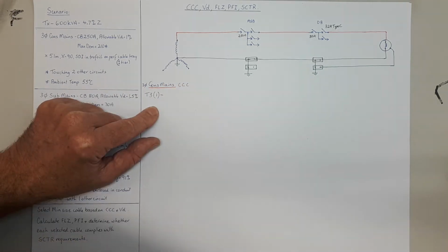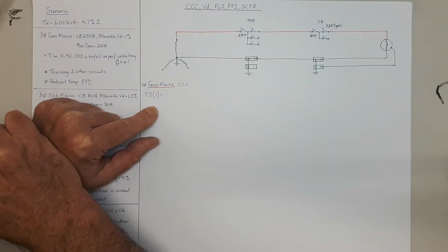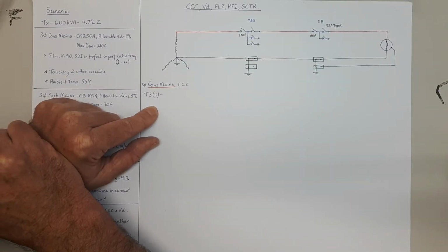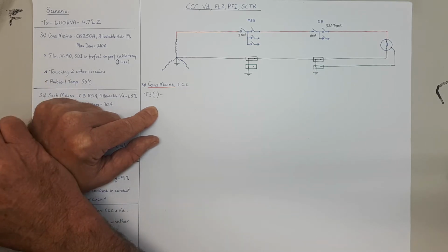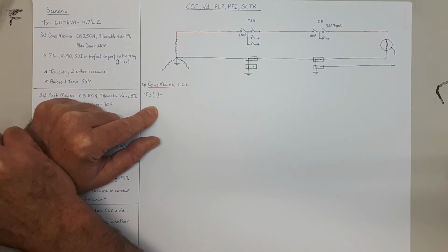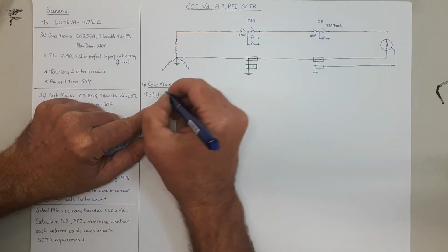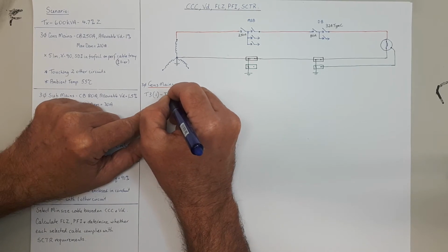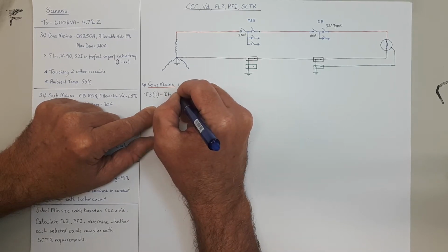And if we scroll down, we find we're looking for cables in trefoil. So if you go to 3.1 and scroll down, we want single core cables. So it's on the first page of 3.1. Scroll down and find it's on cable tray, so that's item 5. So this is the line that we look for, that you've started out correctly.